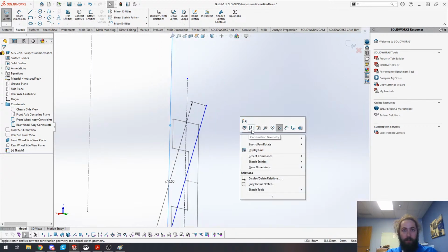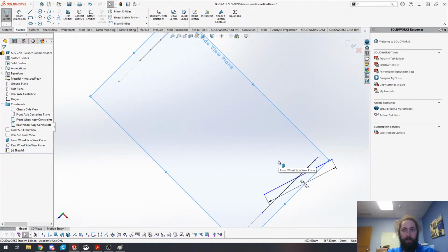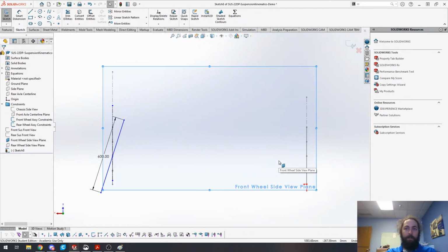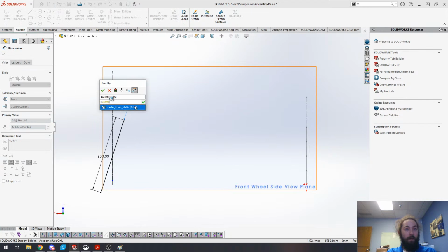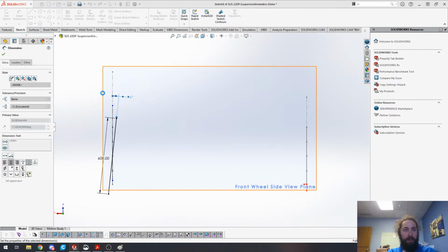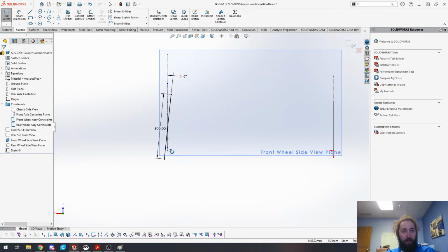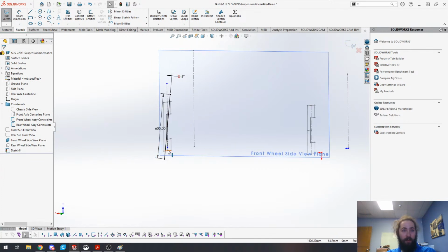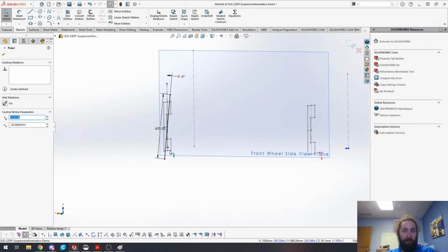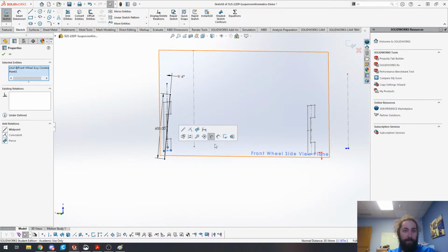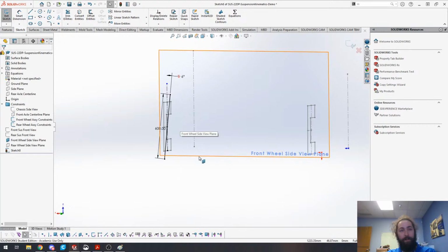We always want to make sure that our references are all consistent. So going back to this view, here we'll set our caster angle. Cool. And we set that at 6 degrees at static conditions, which is fairly reasonable. And then from here, last couple things we need to do are, actually I'm going to make this bottom point pierce where the tire is going through. Cool.